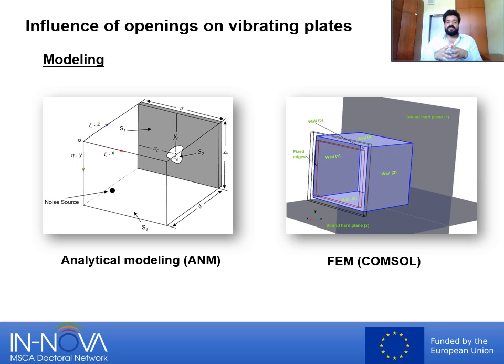To start, we need a model. So first we used an analytical modeling using Rayleigh-Ritz methods, which give the flexibility to introduce our system to different programming languages, and also it's faster to be processed. And also we used finite element modeling using COMSOL to give some visualization of the interaction between the sound pressure inside the casing and the vibration of the plate.